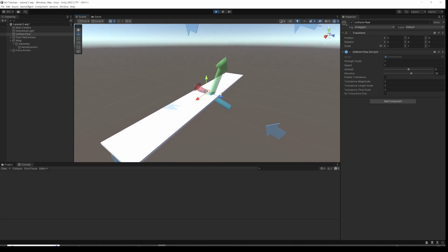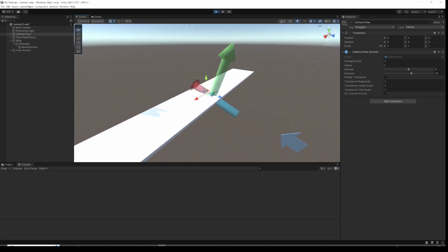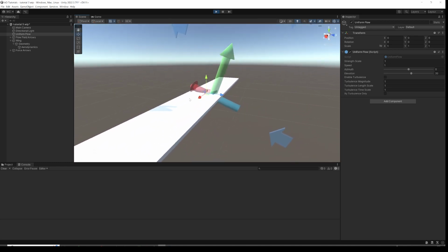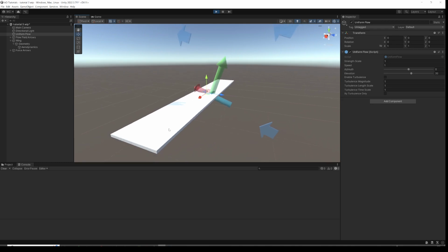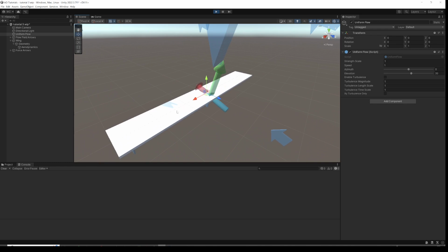From a technical perspective, the location of the lift is called the aerodynamic center. If we've got a flat plate wing like this, the aerodynamic center is coincident with the center of pressure, which is probably an easier concept to understand. If you imagine we've got a pressure distribution on this wing, it's where, if you added up all the pressure, you would put your finger to balance it.